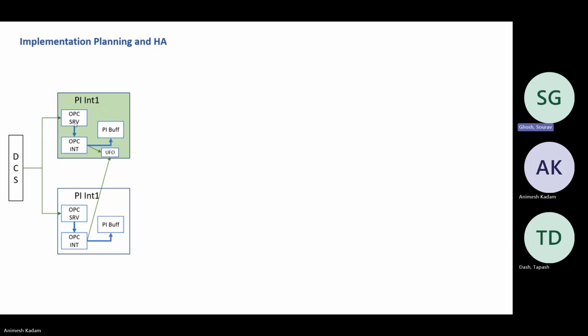So definitely, if these OPC servers are different, when you configure the OPC interface, the ID will also be different, right? Right, because they are different. Now, because this is interface level failover, I am only considering that once this interface goes down, the other will take over.